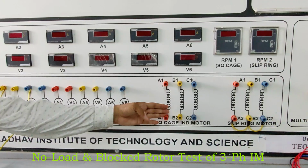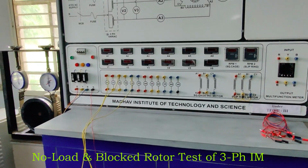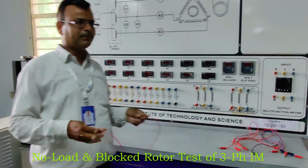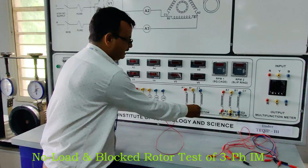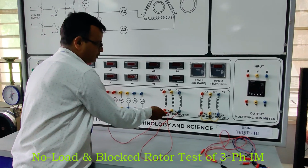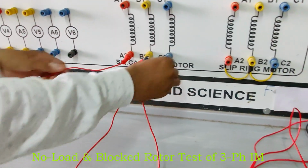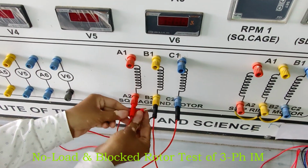So we are considering only star fashion. Clear? And how to connect in star? In a star fashion, you have to create a neutral point or star point. See that this is the same connection here. So these are common points or neutral points like this. These terminals connect here and this one here. So it is the neutral point.